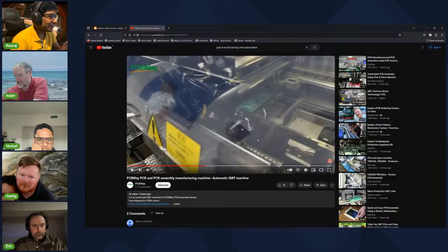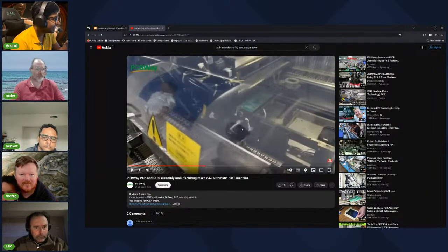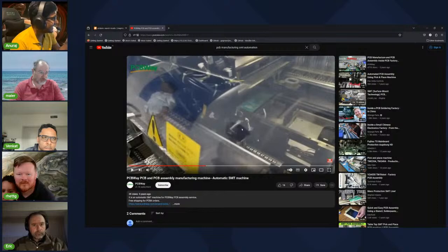And then you have to be really careful about how the reel is placed, because the components also have an orientation, and sometimes for small components the orientation might change and you might not know. I have debugged problems in which the components were shifted 90 degrees, and everything would be correct, the hardware would be correct, the software would be correct, and you wouldn't know why the problem is happening.